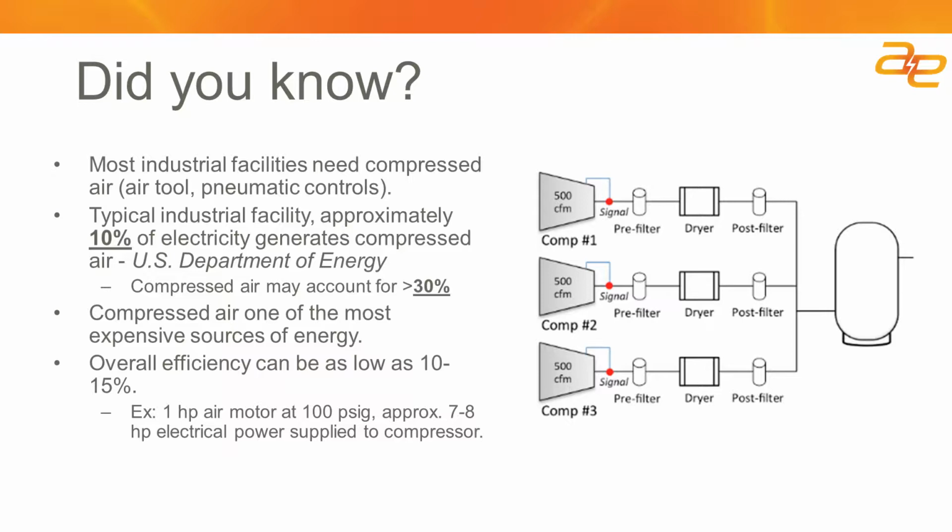The reason is that a lot of the manufacturers that make boilers and chillers for producing steam and chilled water often have pre-developed control solutions that they can implement within a facility for managing the sequencing of chillers and boilers. But the compressed air industry and marketplace hasn't been as forthcoming with designs that incorporate equipment sequencing.